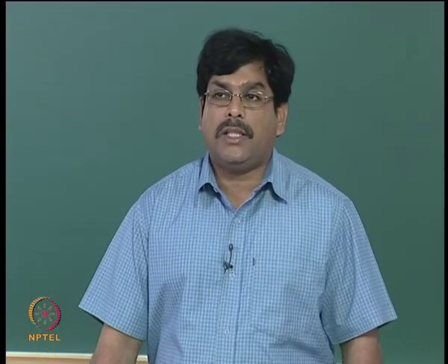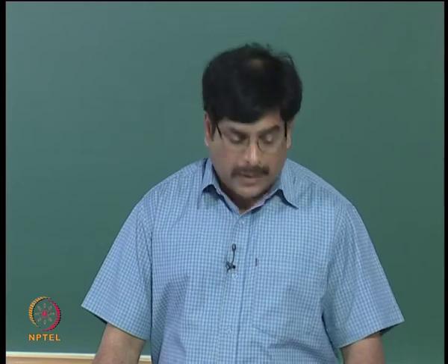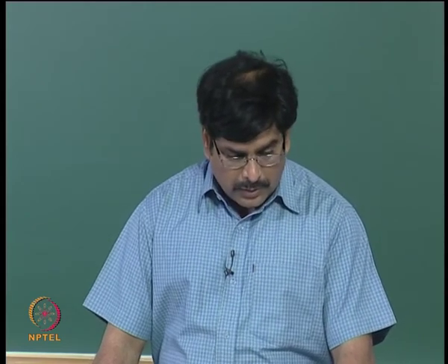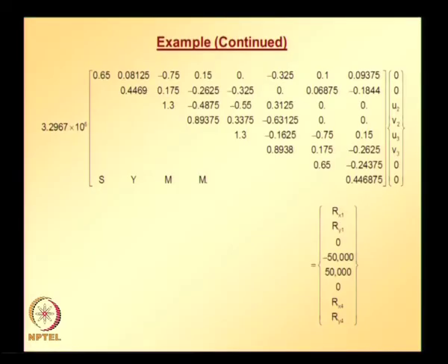So, using this information we can assemble element equations, noting essential boundary conditions. The global equations are as follows. Essential boundary conditions are also specified here in the equation system that is shown. Please note that node 1 and node 4 are fixed, so displacement in x direction and displacement in y direction at these locations, that is at node 1 and node 4, are 0.